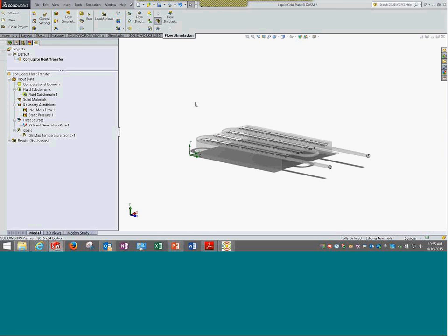Now, one important thing I would like to highlight: typically, we all know that Flow Simulation cannot handle phase change, that is, water turning into steam and the other way around. Saying that, customers may not speak the same language, and they may just ask us, can you do multiple liquids? It could be cases like this, where I have multiple liquids flowing into different domains or subdomains, and that's fine. This kind of behavior can be simulated in the software.